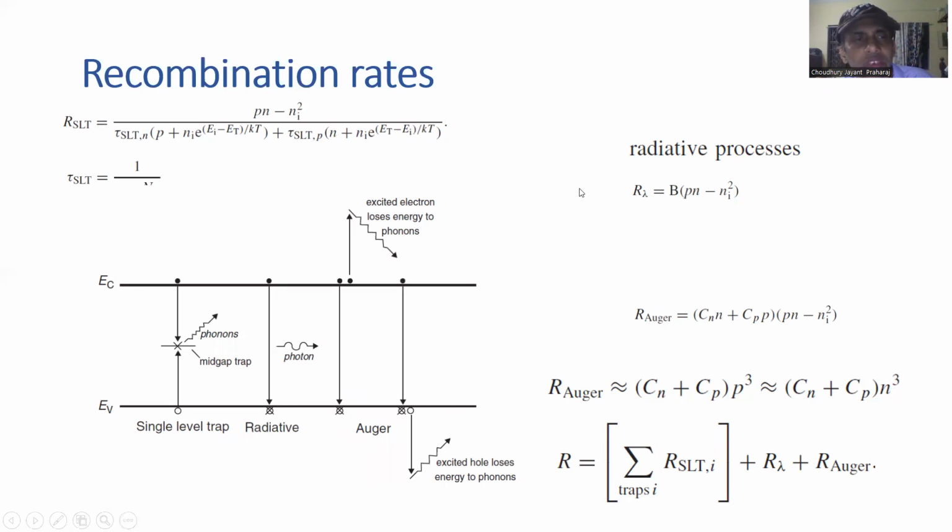While in the non-radiative recombination process, which can be mediated, for example, by defects with mid-gap states, the recombination takes place with emission of sub-band gap or below band gap energy. That energy is basically lost and cannot be retrieved inside the solar cell. And then you have the Auger recombination. The total recombination rate is the sum of all these different kinds of recombination rates.